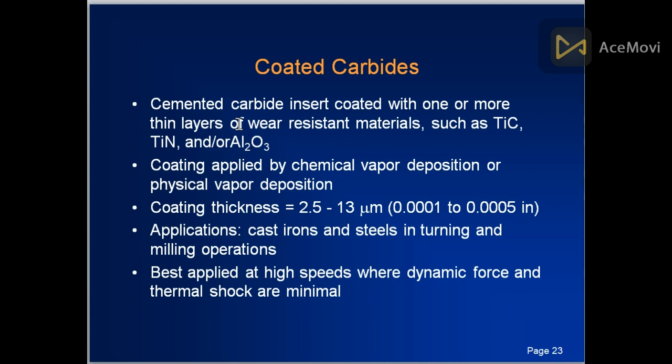Coated carbides are cemented carbide inserts coated with one or more thin layers of wear-resistant material such as titanium carbide, titanium nitride, or aluminum oxide. The coating is applied by chemical vapor deposition or physical vapor deposition. Coating thickness is 2.5 to 13 micrometers.